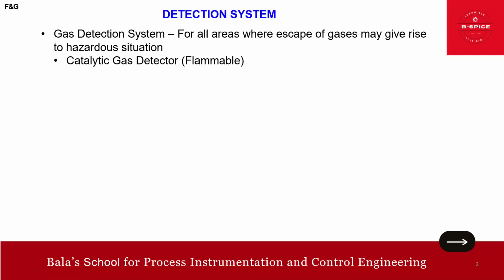The sensor converts this heat, the temperature change, via a standard Wheatstone bridge type circuit to a sensor signal that is proportional to the gas concentration. Very simple. You got it, friends? The sensor consists of a pair of heating coils, reference and active. So this is how it works.